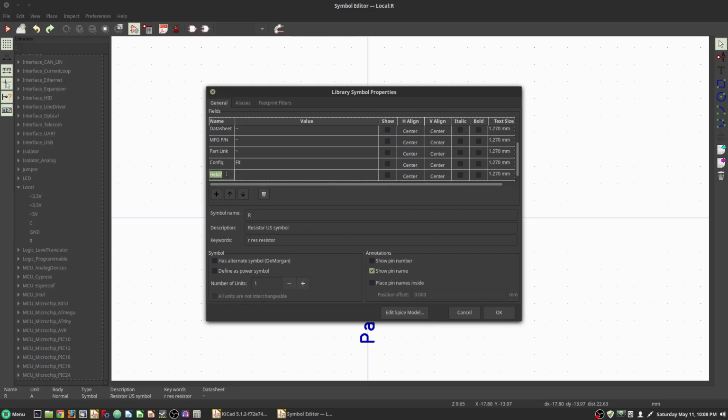The last field I use is description, and this is basically just when I go through and grab the descriptor from the website such as DigiKey or Mouser. So I can know what the value is, what the tolerance is, the package size. With capacitors you might want to know your temperature coefficients as well. And that way if you ever have to send this off to a fabrication house or an assembly house, they can find new parts based off of what you've spec'd, and this will all be listed out in the bill of materials when we get to that point.